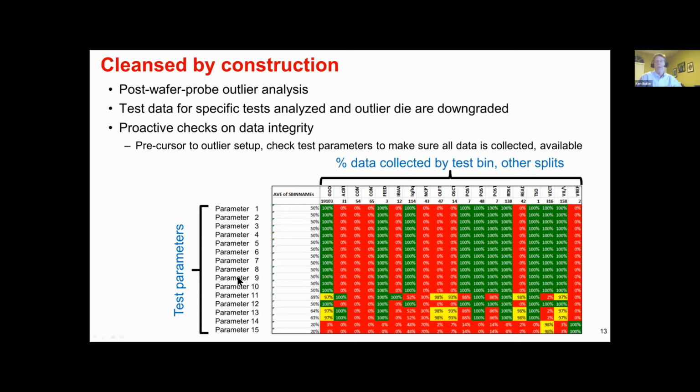Why would that be? Well, many test programs, at least in the analog space, begin as characterization programs where you're collecting an enormous amount of additional information about the part when you are characterizing it and trying to learn the silicon's behavior and look for things where you might have yield detractors or maybe design weaknesses that you want to go and correct in a later tape out. So we may have a test program that initially has many hundreds or thousands of parameters, but not all of which are needed for production tests. They're more for learning at the beginning of the cycle.